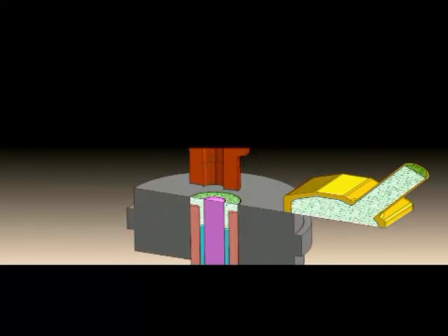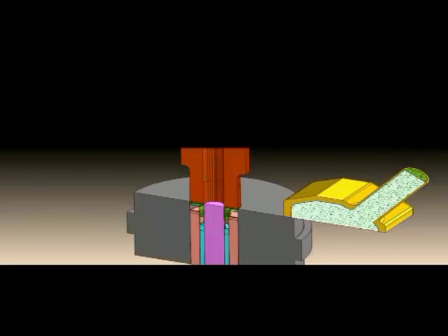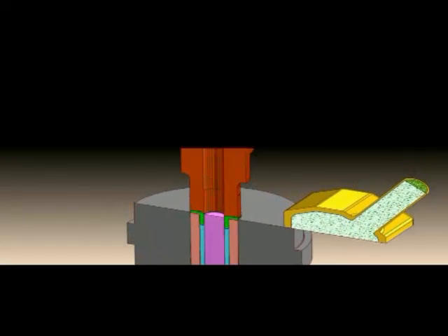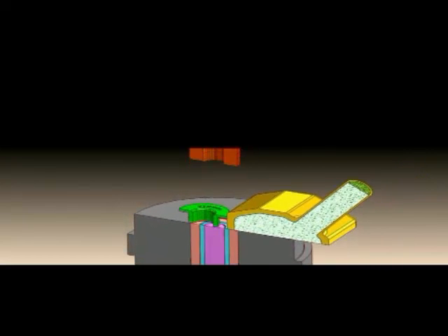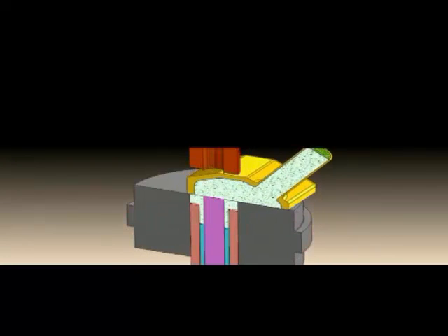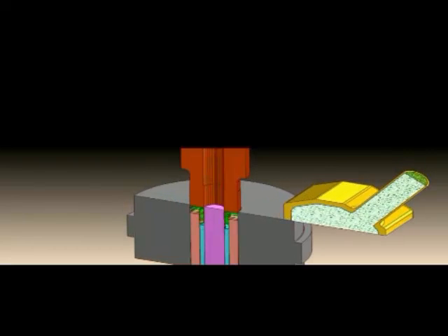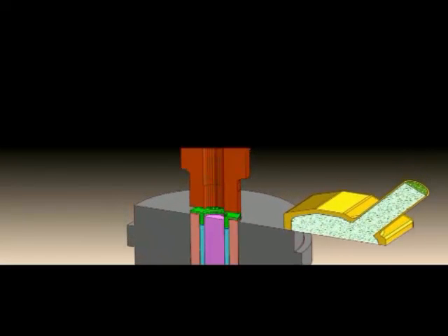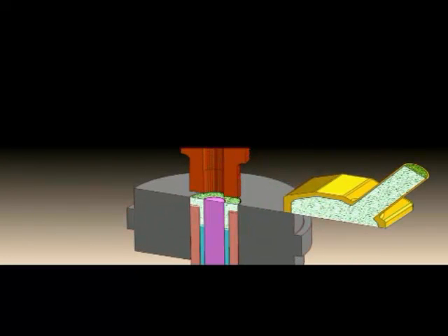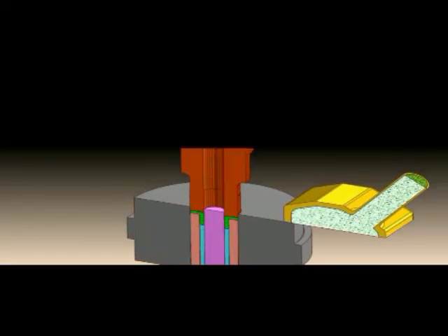Tooling costs, let me just get a quick thing out there. Certainly in PM101, we all have that interest in tools. What do they cost? A typical tool to produce a small straight gear is maybe around $5,000. If it's a very complex, large, multi-level gear, it might be up to about a $15,000 expense for that first set of tools.